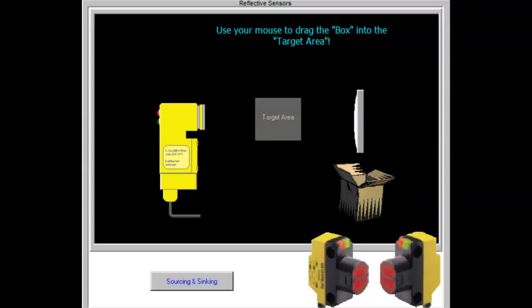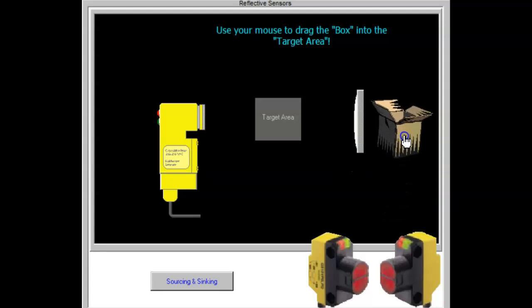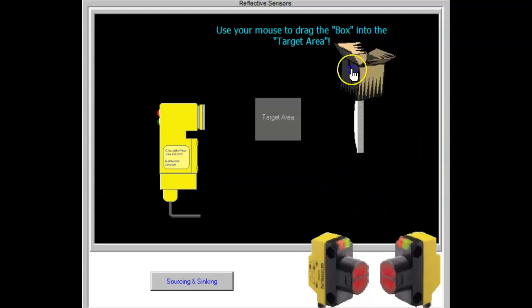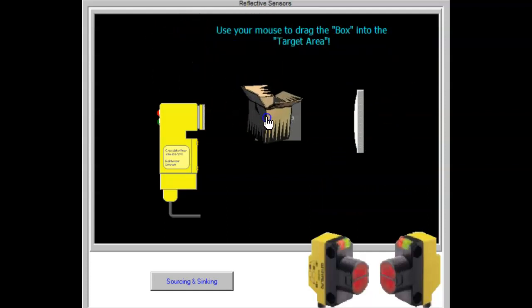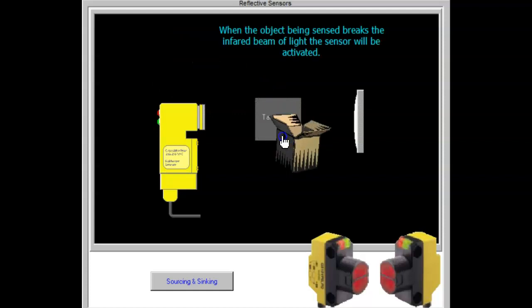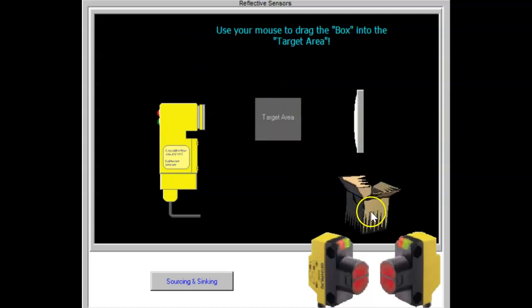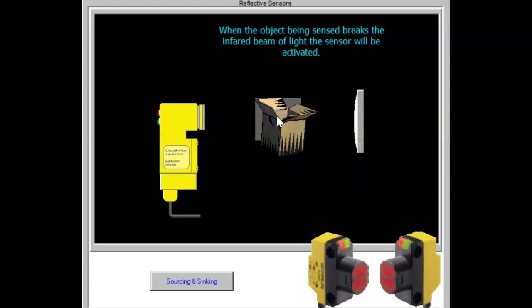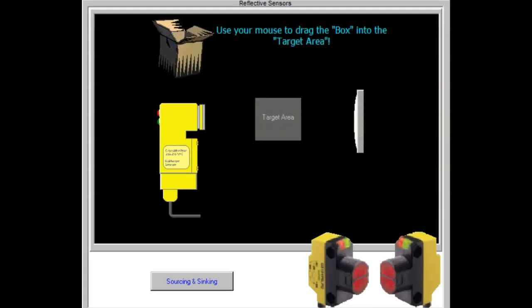Alignment is not critical with these types of sensors. The light source photosensor may be up to 15 degrees either side of perpendicular to the target. Because alignment is less critical, retroflective scanning is an excellent way to counteract vibration. Retroflective scanning can be used at distances up to 40 feet in clean air conditions. As distance increases, a larger retroflective target should be used to intercept and return as much light as possible. Single unit wiring and decreased maintenance are also advantages to this method of scanning. This type of control is also available using fiber optics.